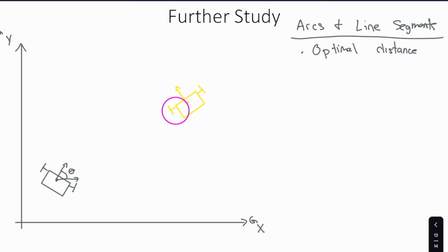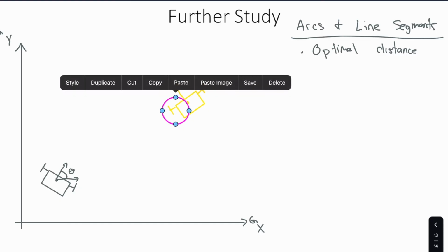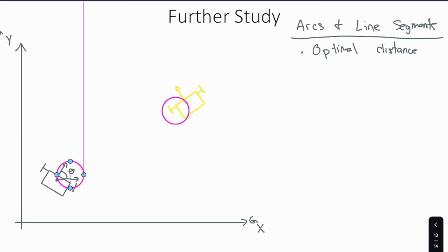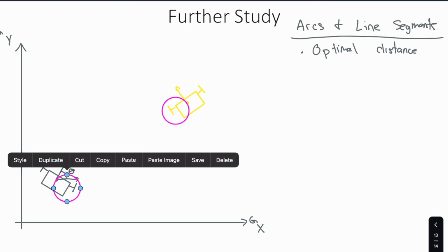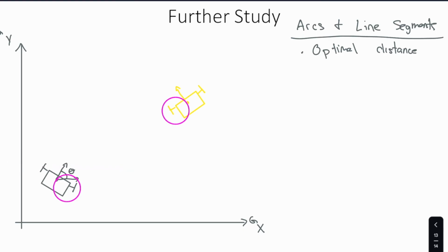You also define a circle of the same radius where your current heading is a tangent on the circle. And finally, you connect the two circles by their closest points. And finally, your path is given by traveling around the first arc, on a straight line, and then around the second arc. And you're guaranteed to have a minimum distance, so an optimal distance traveled.